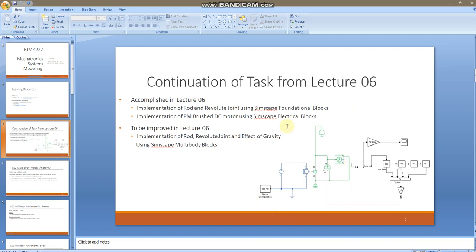On one side, you don't see any kind of math, and on the other hand side, we see some math and math operation blocks. That is because at this moment we still are implementing the effects of gravity through the evaluation of expressions that we have specified. This too can be relegated to a ready to use block, a Simscape block, which will handle the math behind the curtains, and all we would have to worry about is making the proper connections between the blocks.